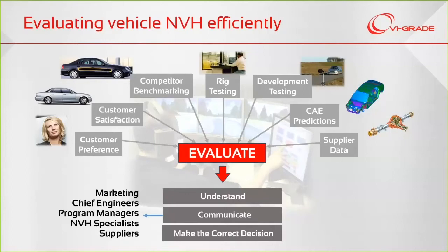What you need to do is take that data, translate it into the interior of the car, apply a transfer function to it so you understand what that means inside the car at the driver's ear, mix it together with all the other data that's there, so all of the road noise and the wind noise and the other engine noise and anything else that's going on in the car. Then you can listen to it in the right context and understand what that really means to the overall design of the car.